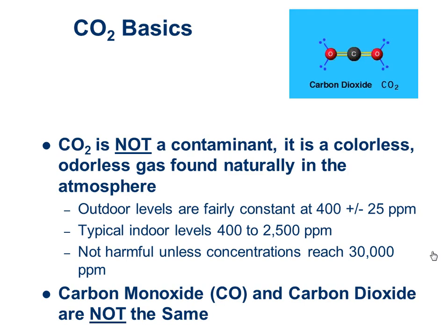Second thing I want to point out is that a CO2 sensor is significantly different than a CO sensor. I know that sounds mundane to most of you. However, every single day I get people calling me asking for CO sensors for their office buildings to modulate their ventilation dampers. So they're not getting it. So I just want to point out CO2 sensors are carbon dioxide. It is not a contaminant. It is not harmful to people unless it's in extremely high quantities that you would not find in nature. It's a colorless, odorless gas. It's all around you. People are giving it off, and plants are giving it off.